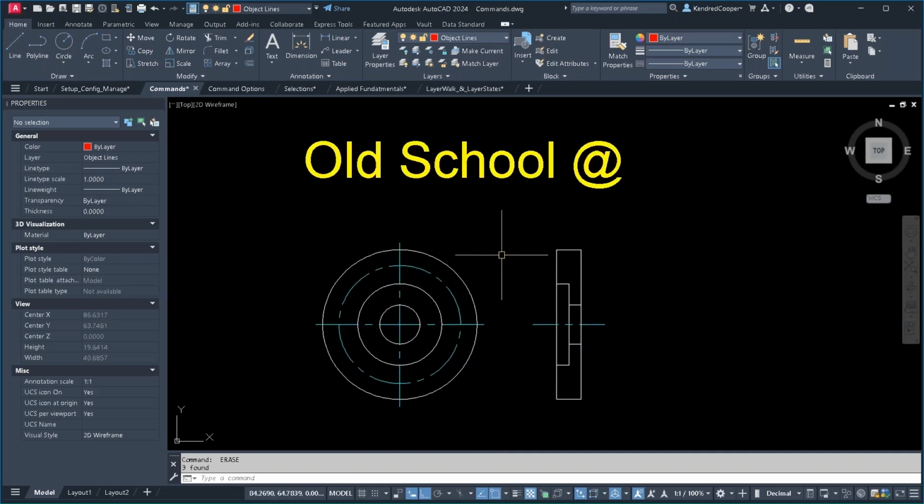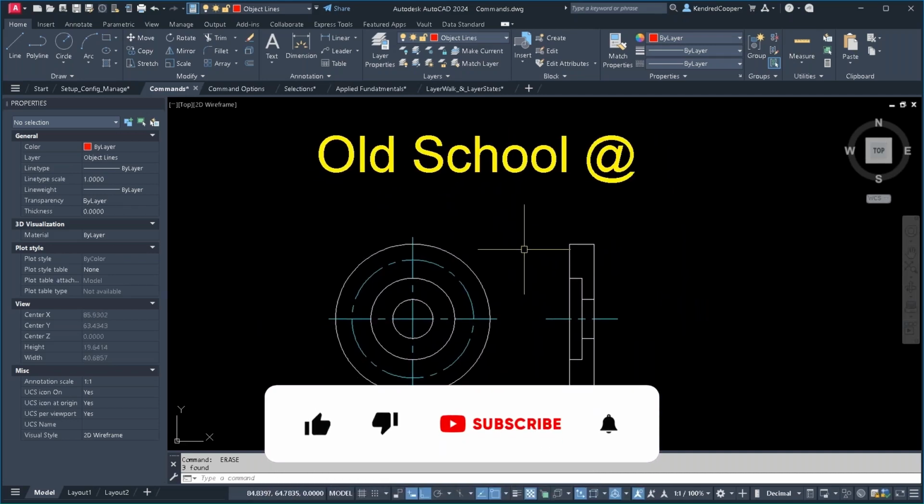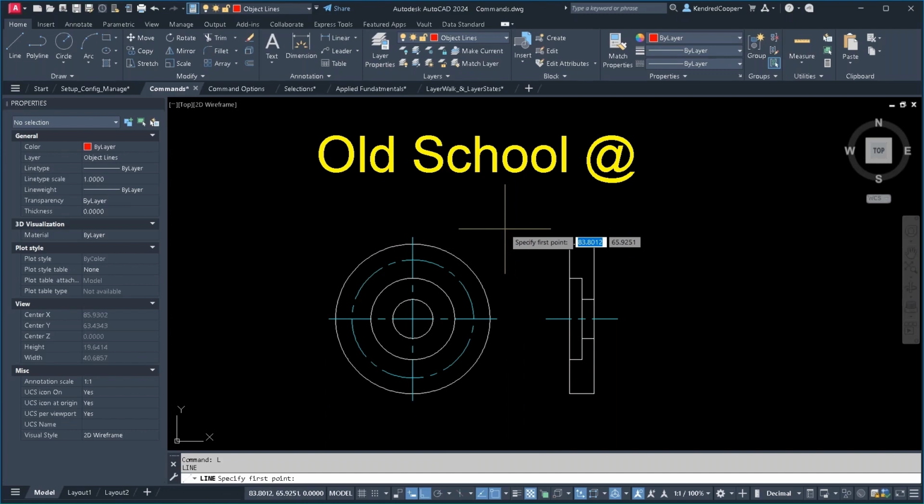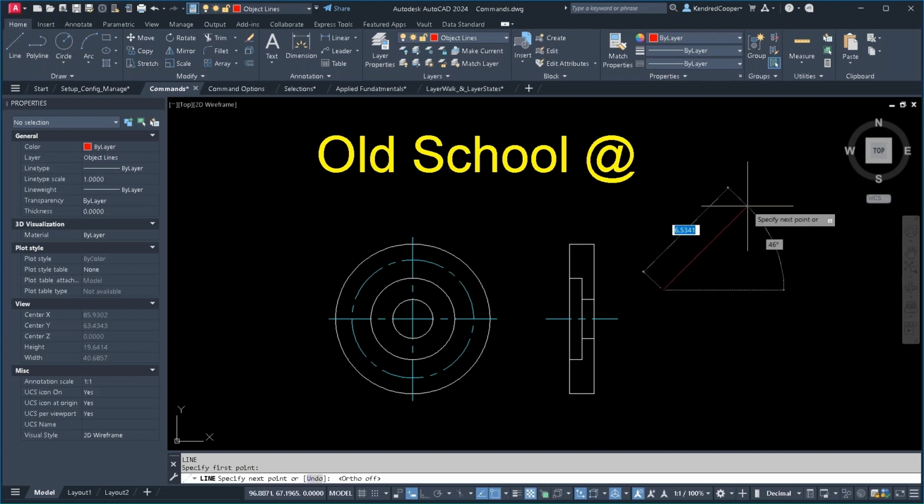Now let's switch over to an old school method of inputting the geometry. So you have dynamic input, which puts the command line at your cursor for most commands in AutoCAD. So if I create a line segment and I want it to be at a particular length or particular angle, this is what dynamic input allows you to do, is cycle between those values.